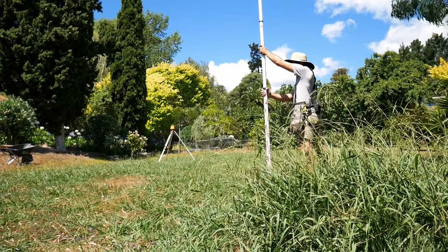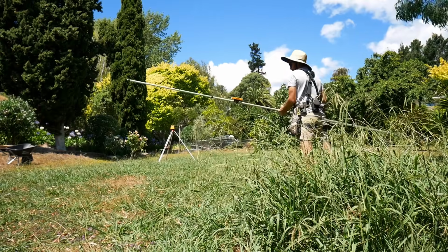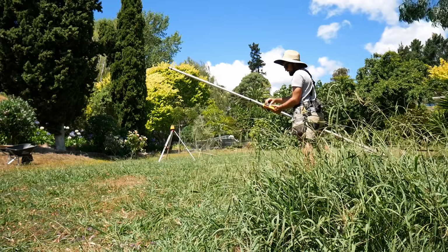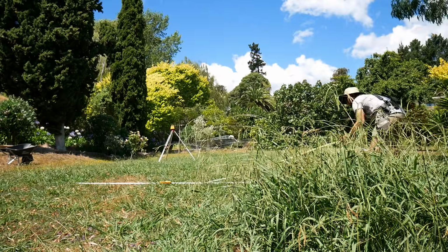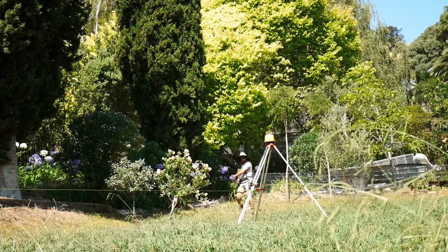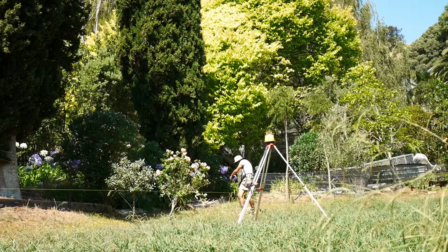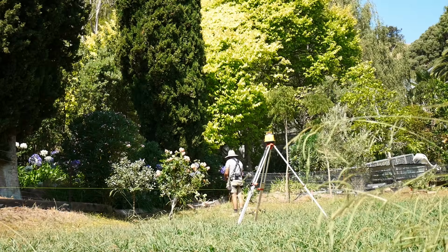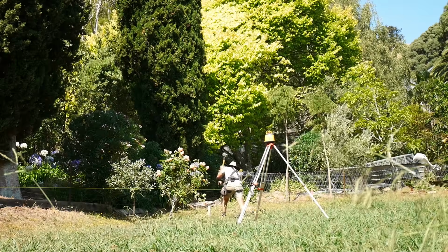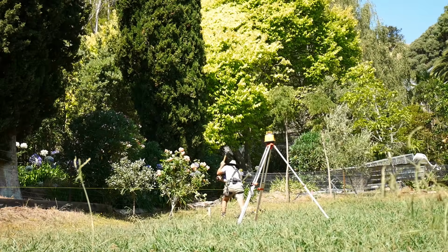That goes beyond the scope of the plans and NZS 3604, the New Zealand standard for timber frame buildings. It would require specific engineering design and significantly impact the height and number of stairs needed to access the home. After discussing it with the relevant parties, my solution to excavate and cut the back corner into the slope was accepted, and the FFL, finished floor level, was adjusted to suit.